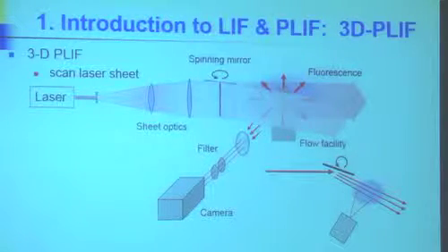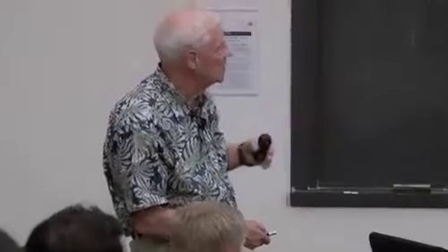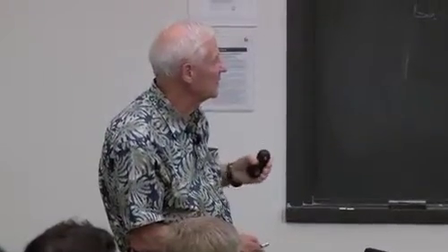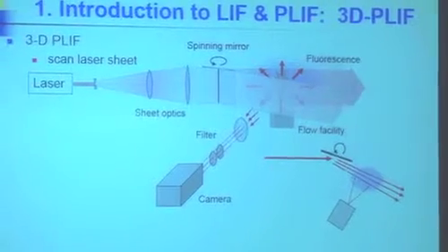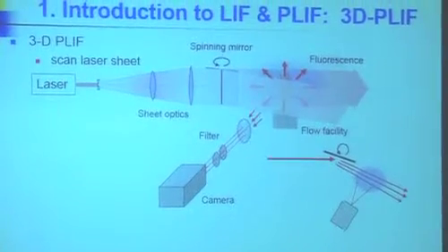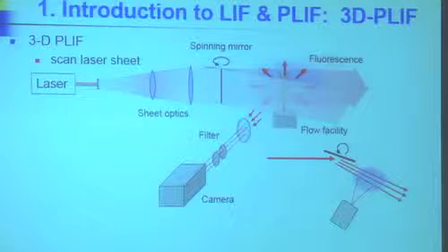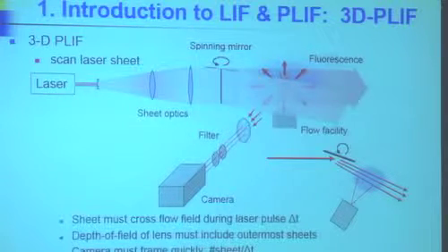Is it a 10 hertz laser? 1 kilohertz laser? The time between the images then is really usually set by the laser. The cameras are usually plenty fast. You can have a camera that goes to 10, 20, 50 kilohertz, kiloframes per second. So typically you use some sort of a spinning mirror or something here, and you can then just move this plane back and forth across your image. So you can do 3D or 4D by an extension of 2D.